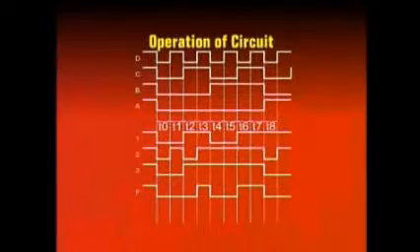The timing diagram describes the operation of the circuit for the product of sum based simplified circuit for the intervals t0 to t8. A, B, C and D are the inputs to the circuit. The timing diagrams show the inputs A, B, C and D changing with time. The timing signals 1, 2 and 3 represent the outputs of the OR gates 1, 2 and 3. The timing signal F represents the output of the circuit.